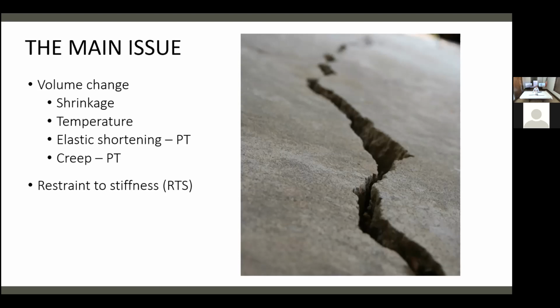And we're not going to get away from that, especially with PT, because PT has additional elastic shortening beyond shrinkage and temperature volume change and creep over time. But all this is fine if we didn't have restraint. So PTI is publishing a new restraint article that's coming out soon. It's just on a committee, so look for that.